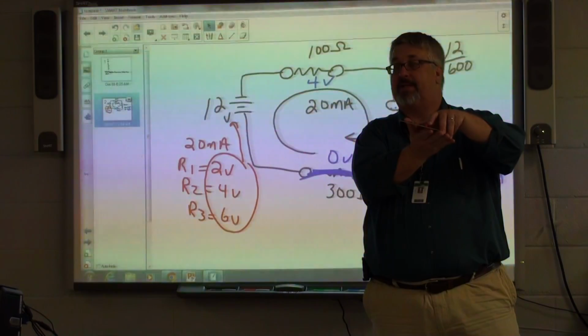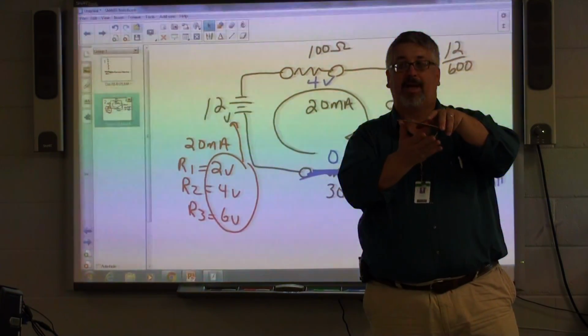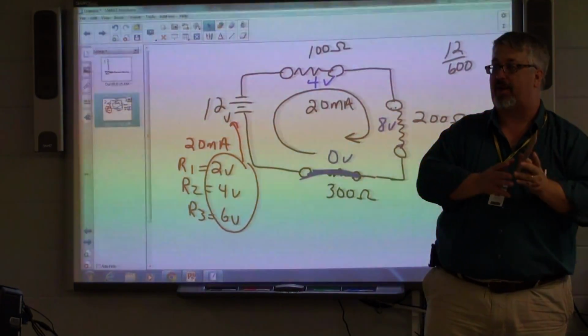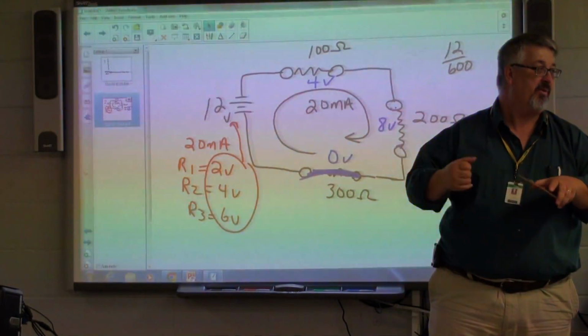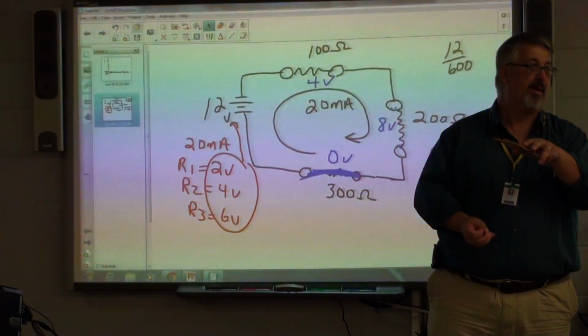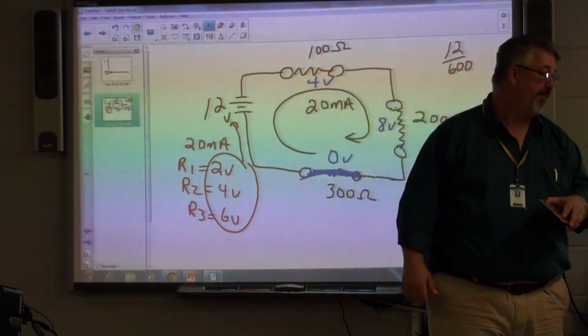And the solder tends to just stick to the metal and run away from the fiberglass. What comes out are these nice, pretty even joints that look like the best solderer in the world did it. But every once in a while, that wave solder machine would burp, and it would splatter solder up on the board, and it would do just what you saw there.